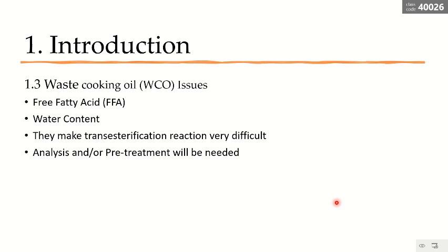Okay, now we know the waste cooking oil has some issues. The free fatty acid there is causing the soaping problem. The water content, if it's too high, will surely hydrolyze the ester and form more free fatty acid.